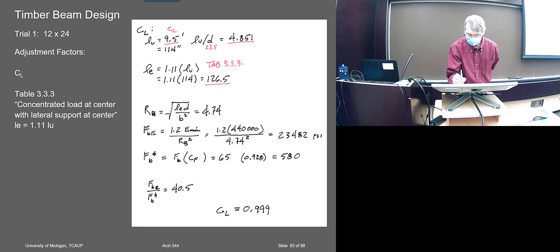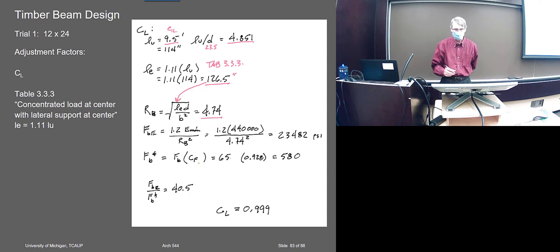So that gives me an LE, right, of 126. So then I put that down into RB, calculate RB. Whoa, very low RB. Oh my gosh. 4 out of 50. So that's at the very highly braced end, and that's because it's so thick, right?